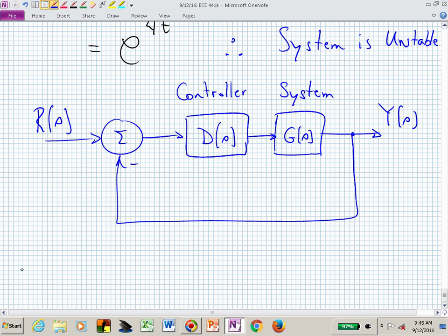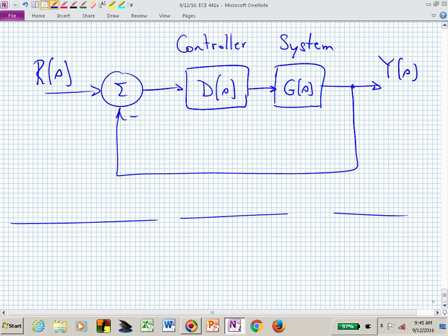And that's what we want to learn how to do, but first we have to figure out how do we create all of these G of s's. You've already spent a lot of time with 4 different representations: state space, block diagram, transfer function, and differential equations, which is what we started with today. And then we had a nonlinear differential equation today. We've then linearized it, found a G of s, and now we can start to control that linear system, capital G of s.